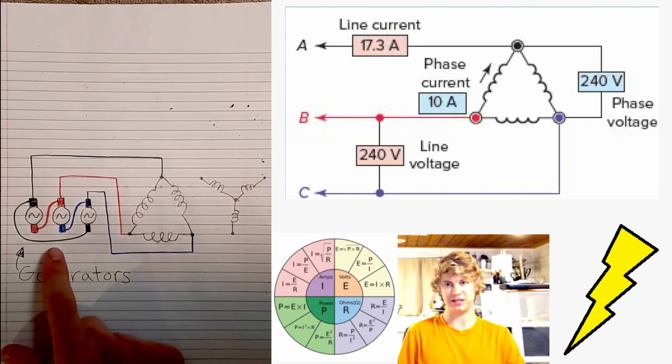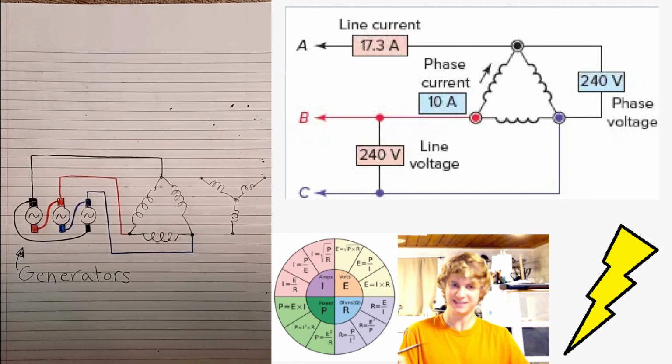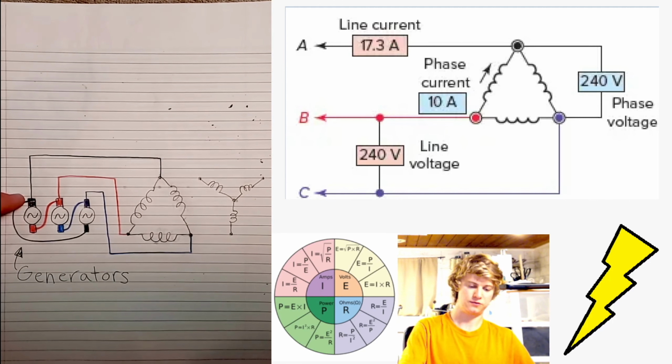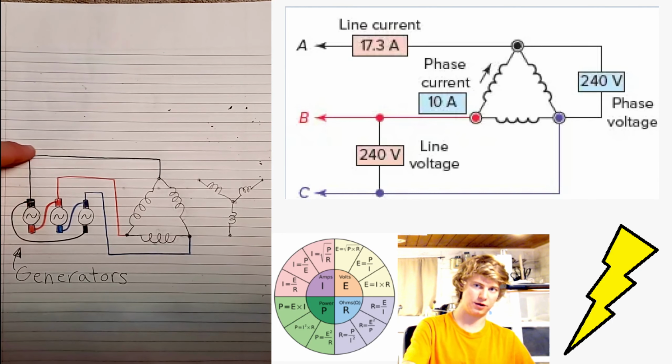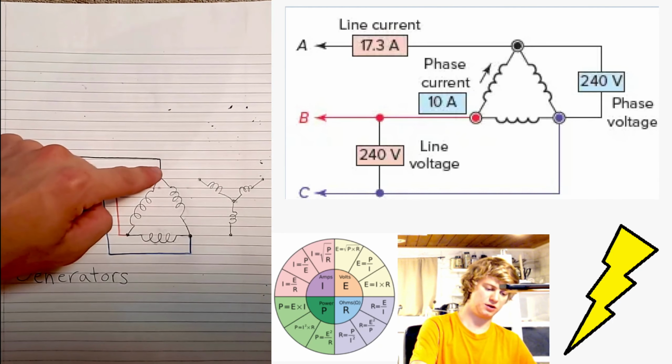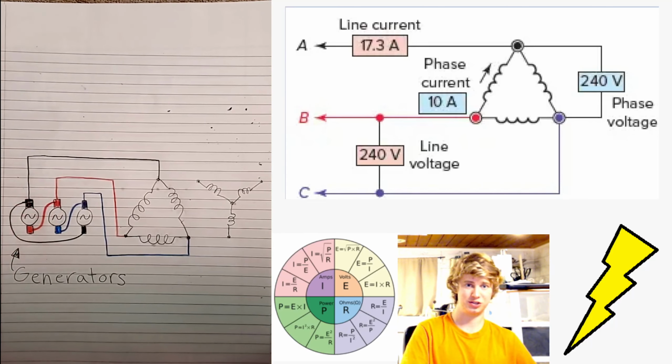We can furthermore see that everything is connected. But furthermore, we can see each of the generators is also interconnected to one another, where everything is connecting to something else. They're not all connected together in every single point, but every single point is touching the point of another phase. First, if we see the black and the red combination, we see a complete loop if we follow the black wire going to its terminal on the alternator, then that going through the rotor to the red wire, where the return of the red wire is connected to where the return of the first generator, where everything started from, is. Because remember, electricity doesn't care about this is a red wire or a black wire.